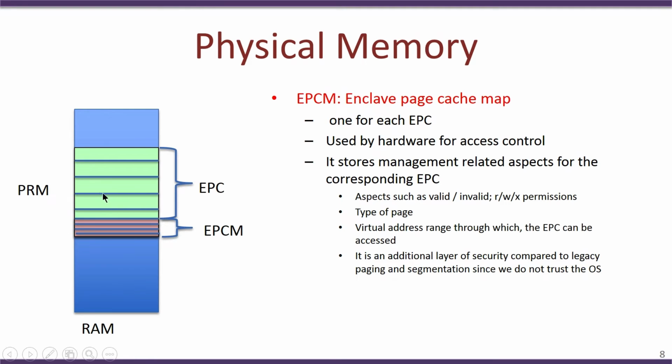For example, this particular EPC would have a corresponding EPCM entry which stores aspects such as the validity of that particular EPC, and the read, write, execute permissions for this EPC. For example, if there is code present over here, you would have that particular code as executable and not writable.